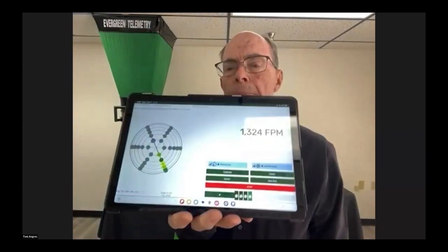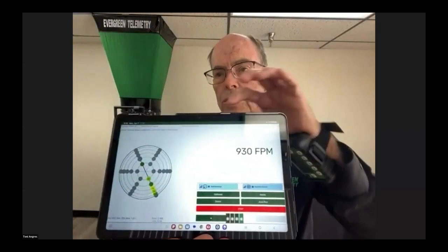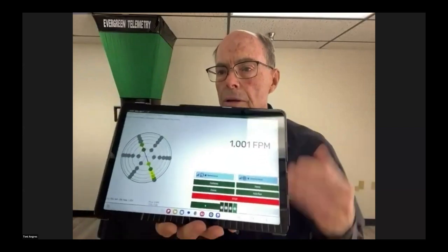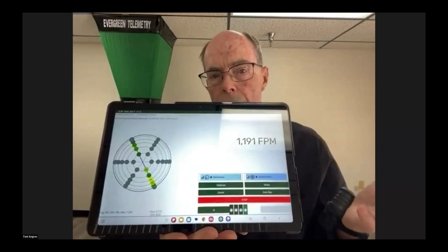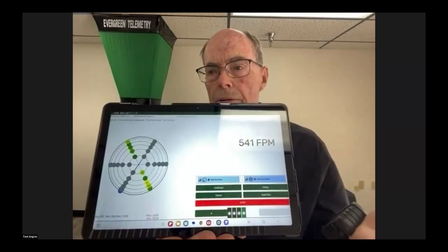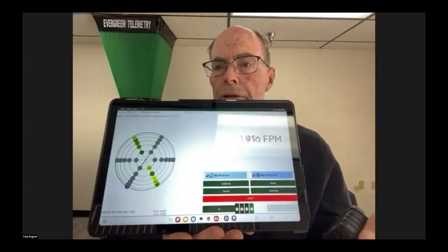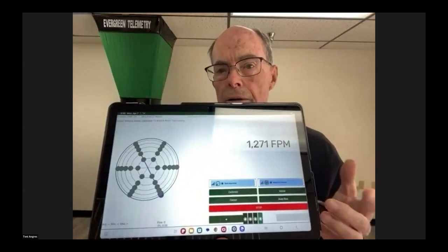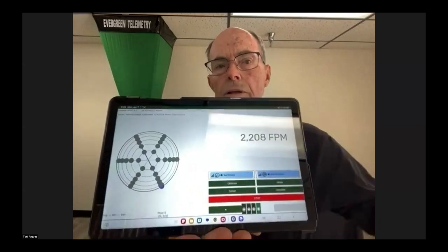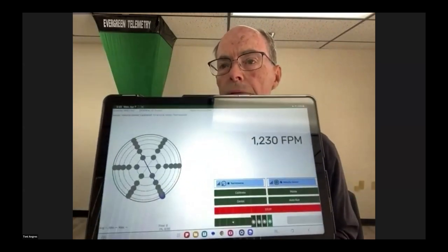This is a simulation. Before you get to this stage, you do the setup and tell the machine the size and shape of the duct and whether you want to use equal area or log Chebyshev. Then you hit start and the machine will perform the traverse for you.